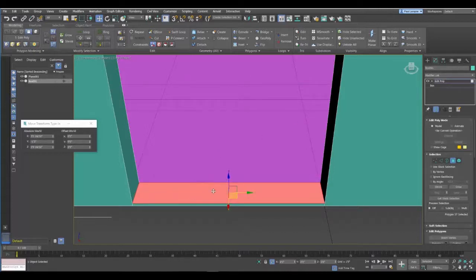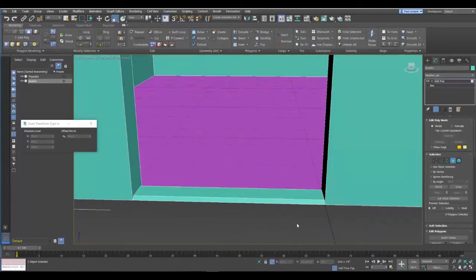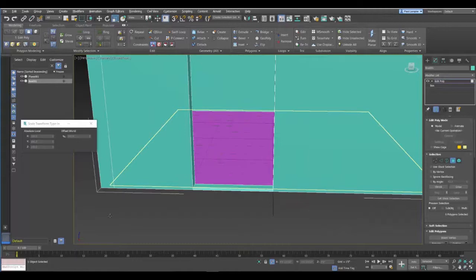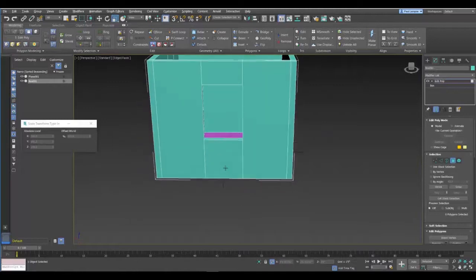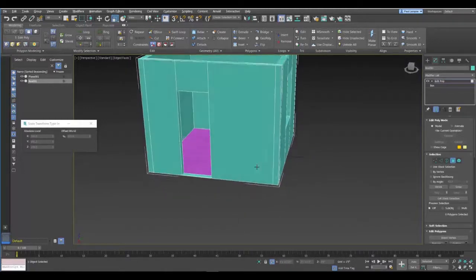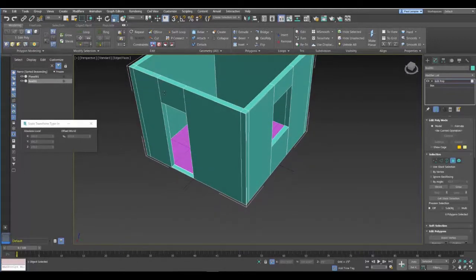And I'm going to bevel this, not by beveling, I did an extrusion, but with that still selected, I can just go into scale and scale in just this one direction to give myself the bevel I wanted on here. Okay, so that's my room. I've got a door and a window, very precisely made to specific measurements, and without creating a lot of excess edges.